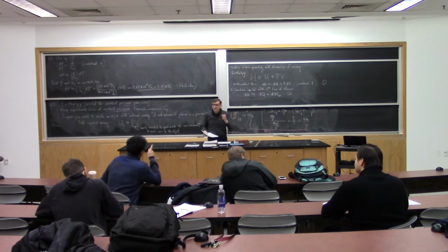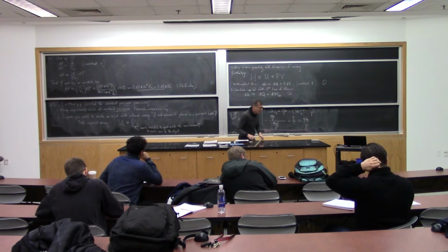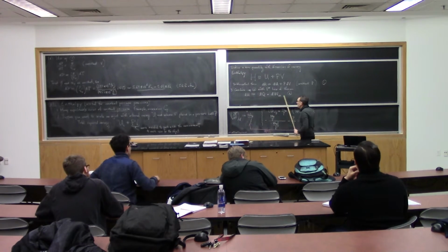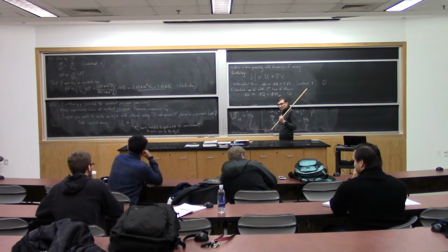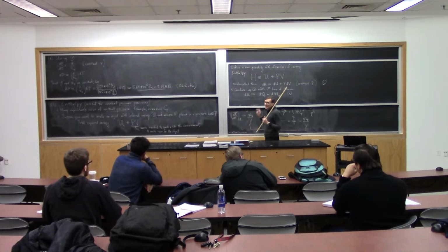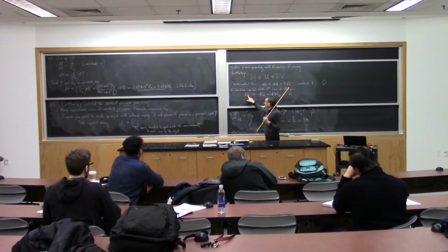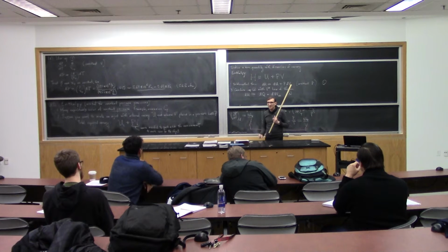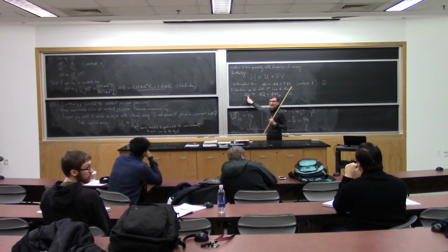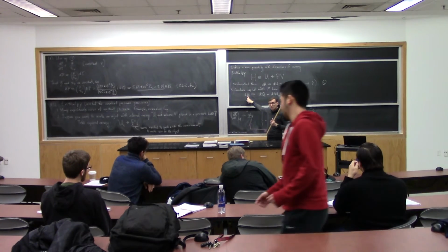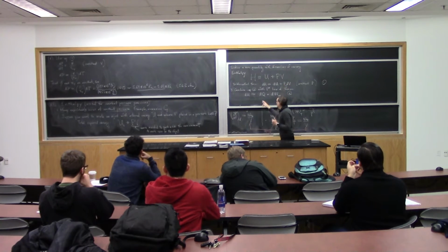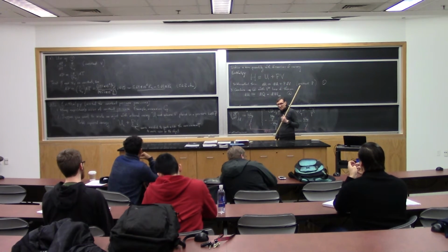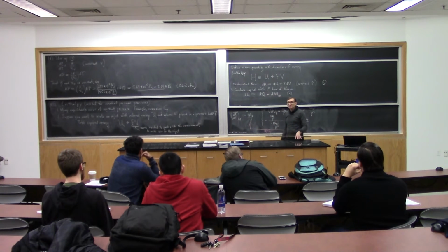Yes? Can you tell me why it is that you put the bar over the dq? Okay, so remember, the bar versus no bar is an important distinction about the physical nature of these 3 differentials. This one is what's called an exact differential. This really means a change in internal energy, meaning that the system had some initial internal energy, U1, and some final internal energy, U2, and this is the difference between U2 and U1. These 2 are called inexact differentials. They do not represent infinitesimal changes.